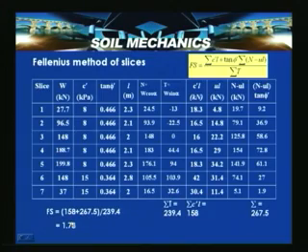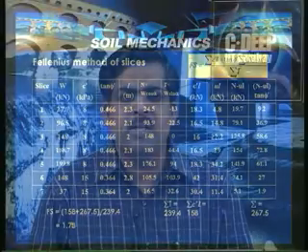A factor of safety equal to 1 indicates that the slope is on the verge of failure, but the convention for static loading conditions, the factor of safety adopted nominally for working stress conditions, is about 1.5. If you consider the 3-dimensional effect of a slope according to the DIN code, it is about 1.4. But there are different loading conditions, like earthquake loading and others, that demand different factors of safety. Conventionally, a factor of safety of 1.5 is adopted under working stress conditions.